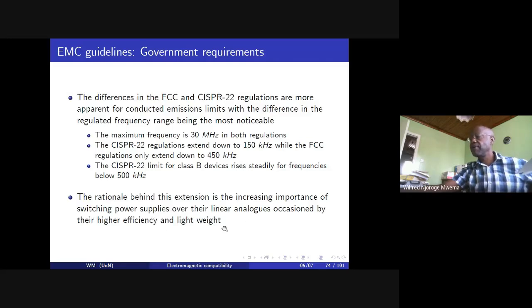You want to have a light power supply, and you'll find that it's much easier to get a smaller transformer if the frequency of the AC supply is higher. So what happens is that you rectify the AC mains directly and then smoothen it to a rough, high-ripple kind of DC voltage.